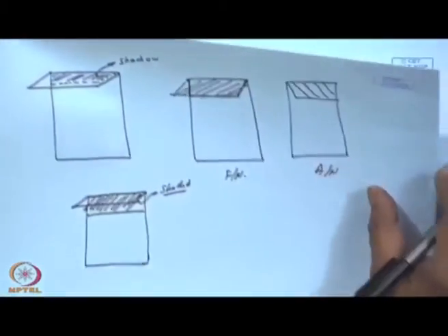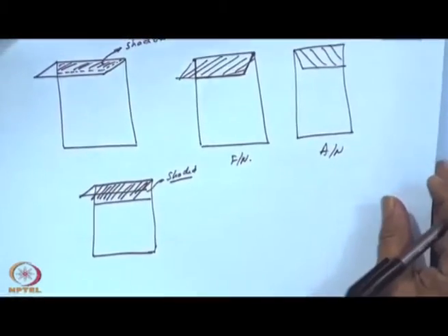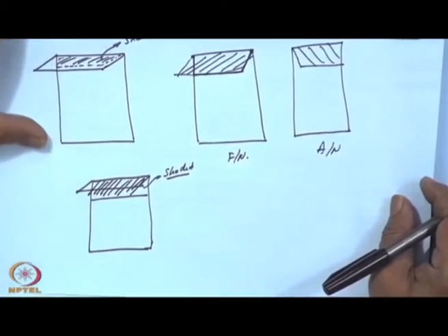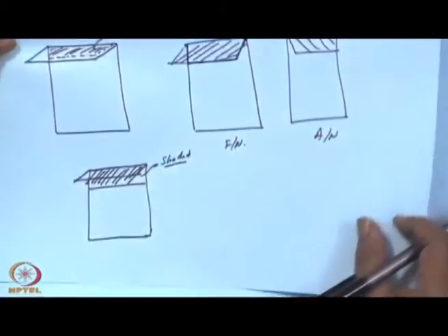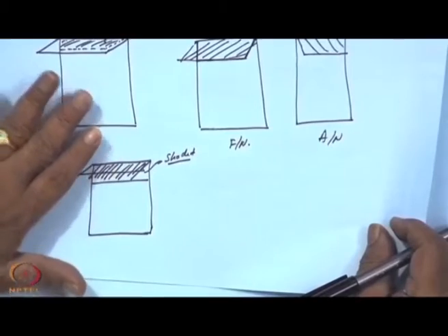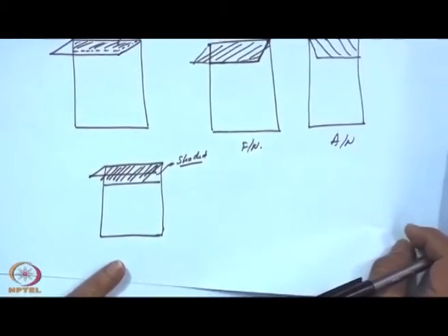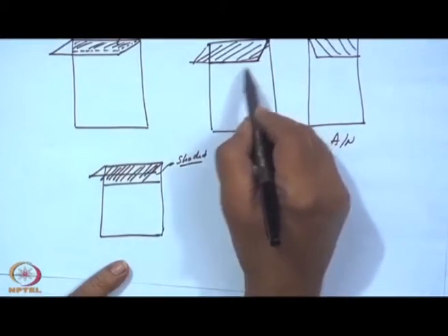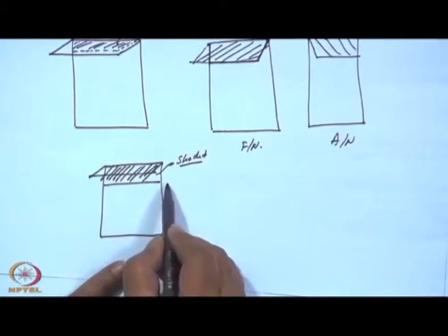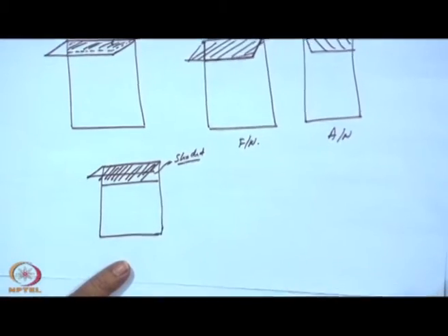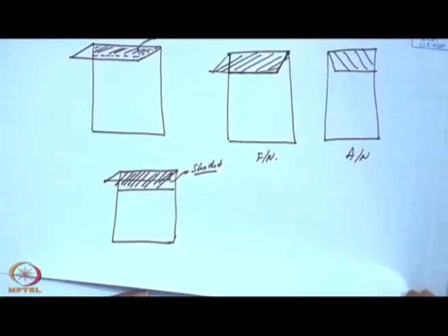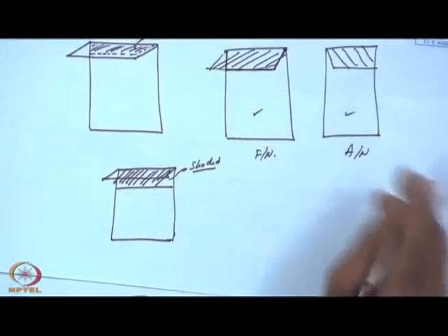Okay. Now, the whole idea is to calculate what is the solar radiation entering through the window with the shadow, shaded by the wing wall. And if it is equal to the width of the window, then I can have a situation like this where a sort of trapezium is shaded, and a complete rectangle could be shaded if it is exactly facing the south, facing the sun, or it could be a degenerate case like the ones I have shown here or here, depending upon whether it is forenoon or the afternoon.